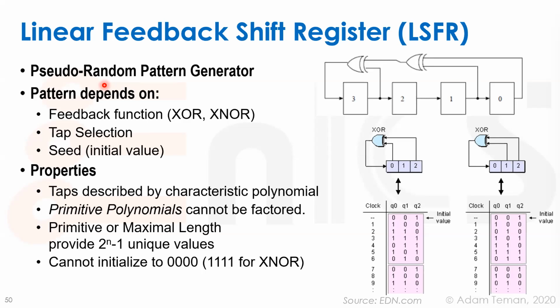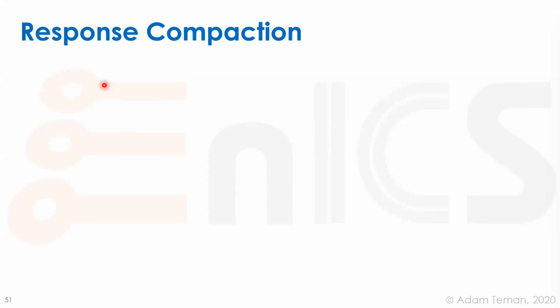And specifically, to test the circuit, we can use this pseudo-random generator. We can put in an LFSR and then make 2 to the power of n patterns with only n registers, which is really nice because if we have a 32-bit input to some sort of a multiplier or whatever, we can just use 32 registers and go through them, and not go through them one after the other, which might not show different types of faults that have to do with just a regular type of step function between them. But how do we check that what we put in is what we wanted to come out? And so that's why we need this response compactor.